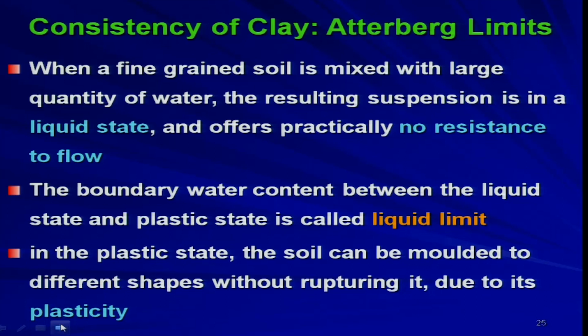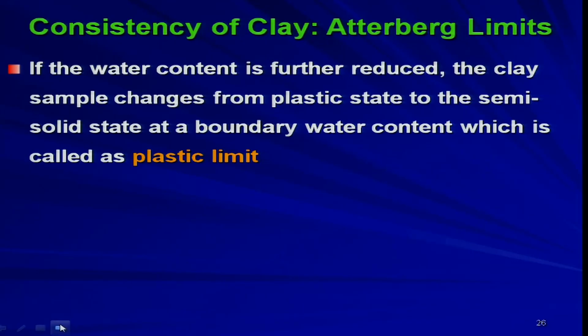In the plastic state, the soil can be molded to different shapes without rupturing it due to its plasticity. As I told you, if you are really interested in clay modeling, you should have the clay under plastic state. If the water content is further reduced, the clay sample changes from plastic state to the semi-solid state at a boundary water content which is called the plastic limit. So, this is the boundary of your plastic state and the semi-solid state.